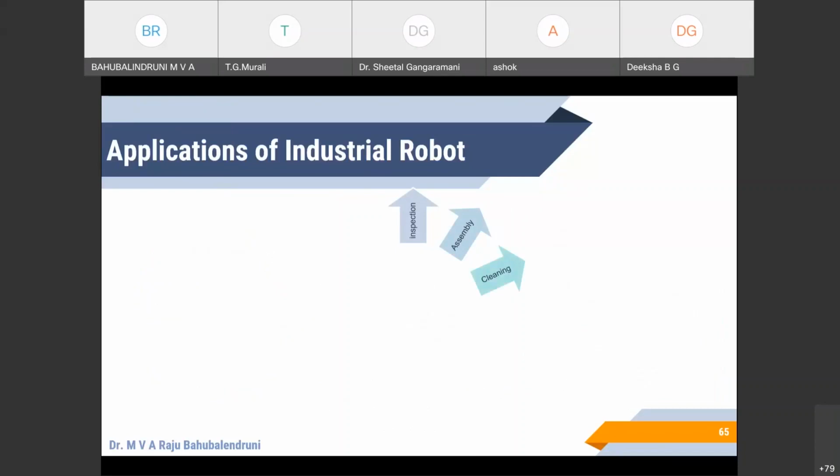Typically, you find cleaning in the energy sector and electronics sector. You need a clean room when you work with nanotechnology, so you have clean room robots. And gluing means when you use adhesives to create laminates. When you do composite laminate manufacturing for the aircraft industry, you are going to use robots for gluing. So it will apply a uniform thickness of glue to the laminas.